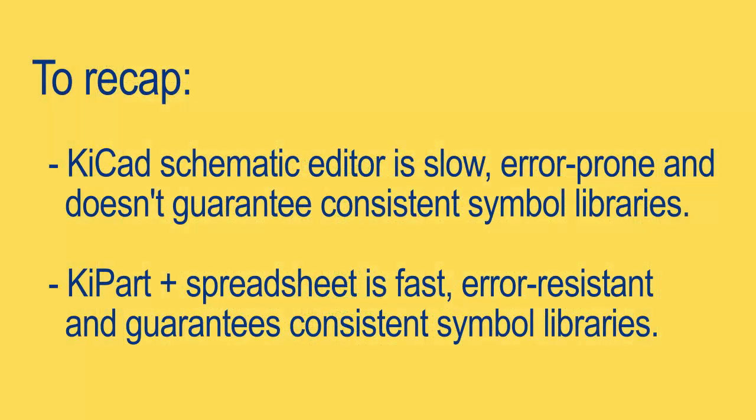Thanks for hanging in to the end of this video. To recap what I've told you, the KiCad symbol editor is slow, error-prone, and doesn't guarantee consistent symbol libraries. The combination of KiPart and a spreadsheet is fast, error-resistant, and guarantees consistent symbol libraries.